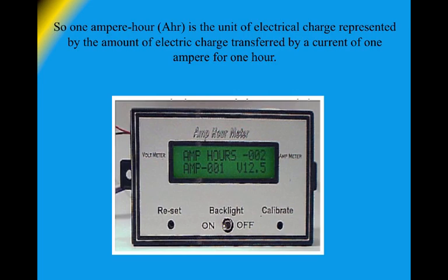Amp hour meters are essential to understanding the actual on-site battery capacity of any given battery, because you are only going to really see what a battery is holding based on the battery's makeup, its amp hour capacity, and the amps put in and taken out of the battery. This can only be done with a very accurate amp hour meter, and attempts to measure capacity with other methods other than specific gravity are fraught with all sorts of problems.